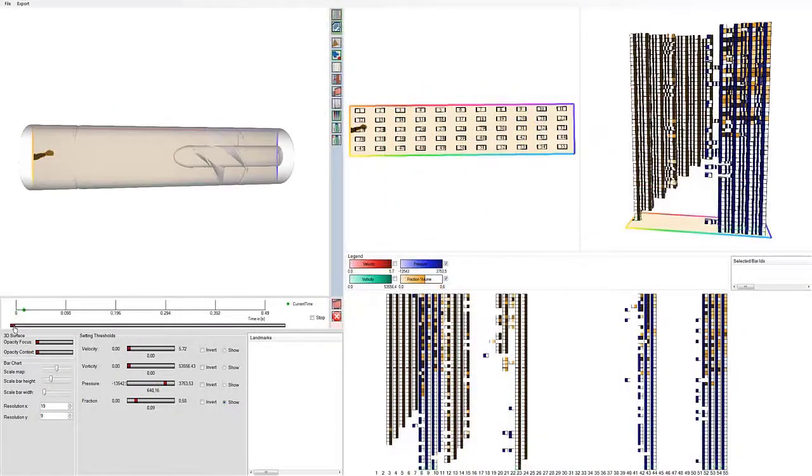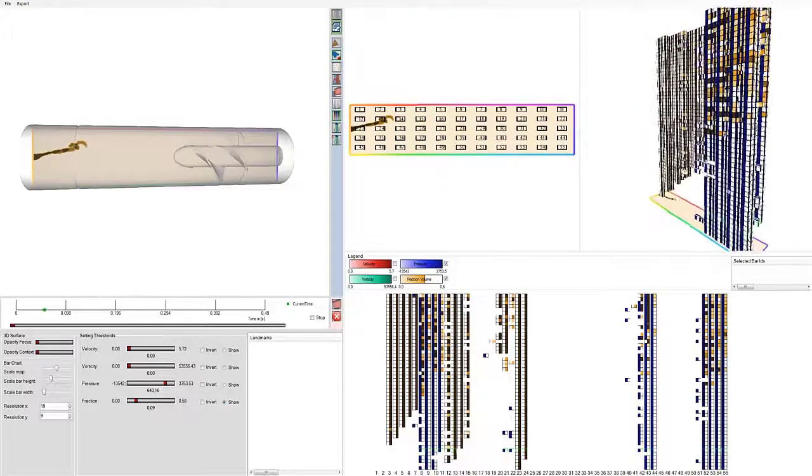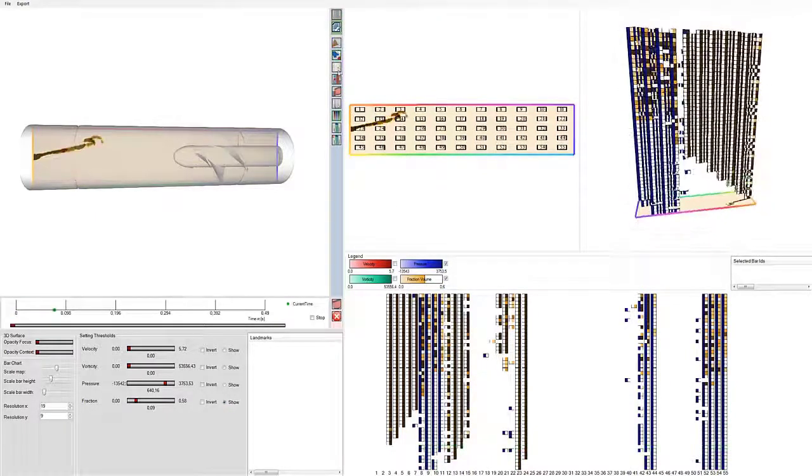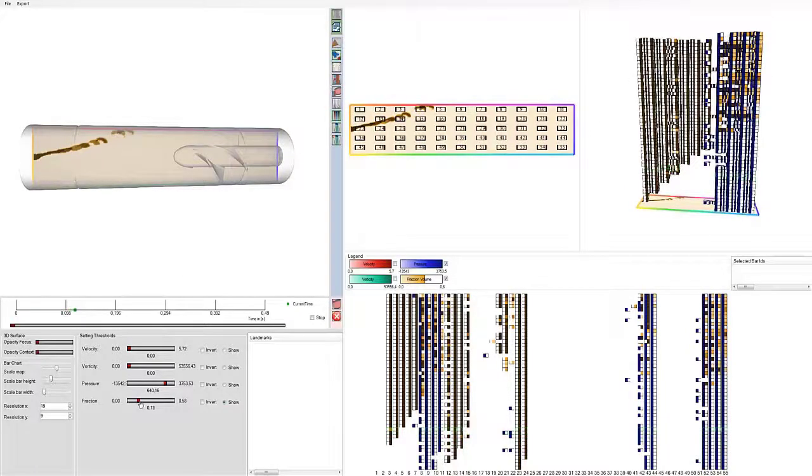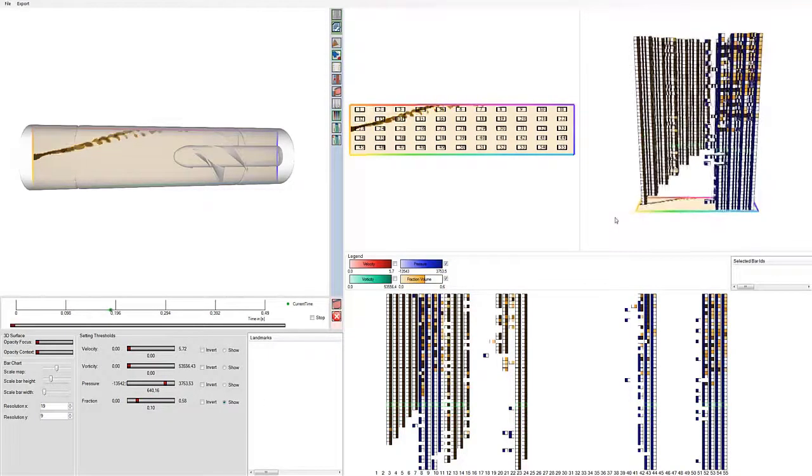By default, the grid cells are unfolded spirally. Depending on the application, it can be better to unfold them row by row. Here you can see the end-user dataset, which was unfolded by this scheme. With this, the user can better observe the reduction of the air volume fraction near the end-user. In addition, the highlighting of the current time step was activated in the skyline visualizations.